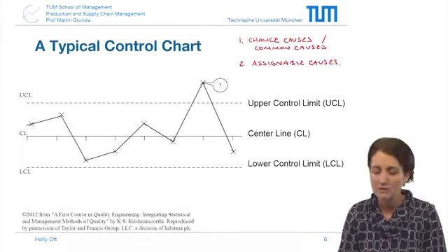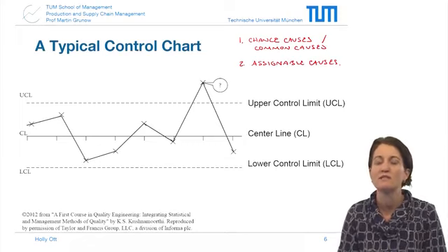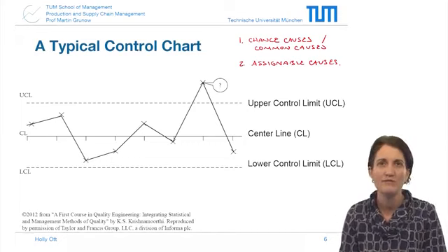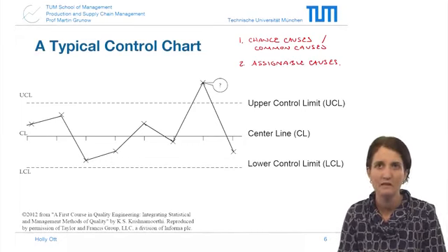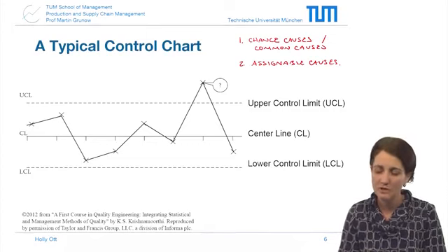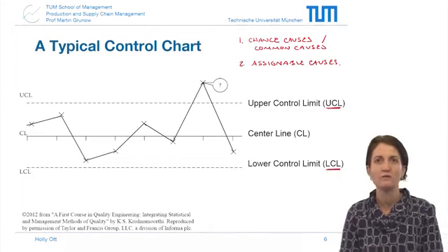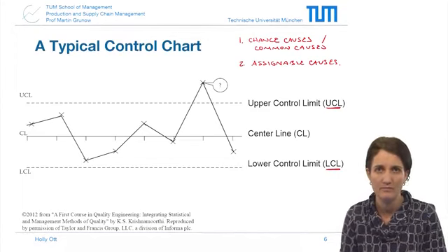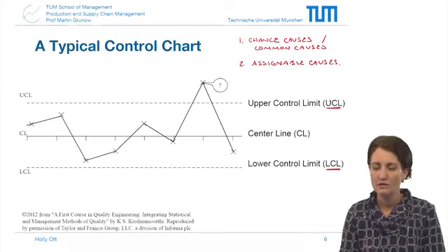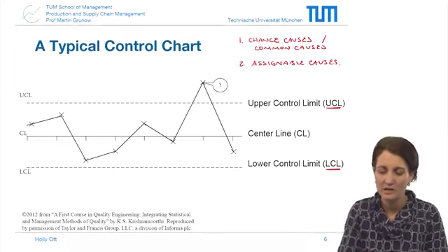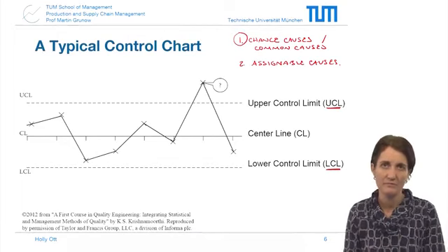But from the assignable causes, this means that we could have a specific occurrence of a broken machine, some problem, some fault, operator fault, something that occurs unexpectedly and unwantedly. So the control limits, the upper and lower control limit of our control charts, then they should be able to monitor the chance causes, number 1 up here.